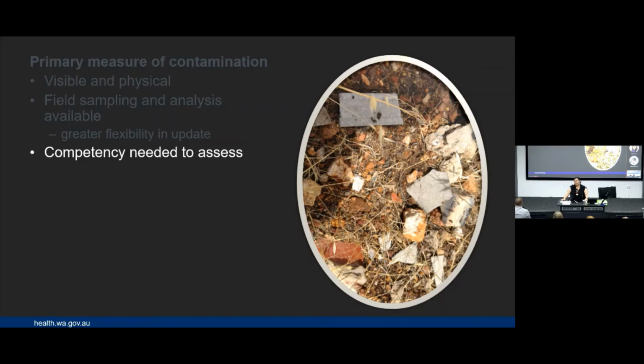Because of that ability to make decisions, because you've got results immediately, because you're looking at a physical contaminant, we do expect the person on the site doing the assessment and guiding the fieldwork to be competent in asbestos. We required that in 2009, and we've reiterated that now. So there should be a person on site supervising those fieldworks, who's competent in understanding asbestos contamination, who can identify some of these products that are difficult to see in soil and relate them to being asbestos.